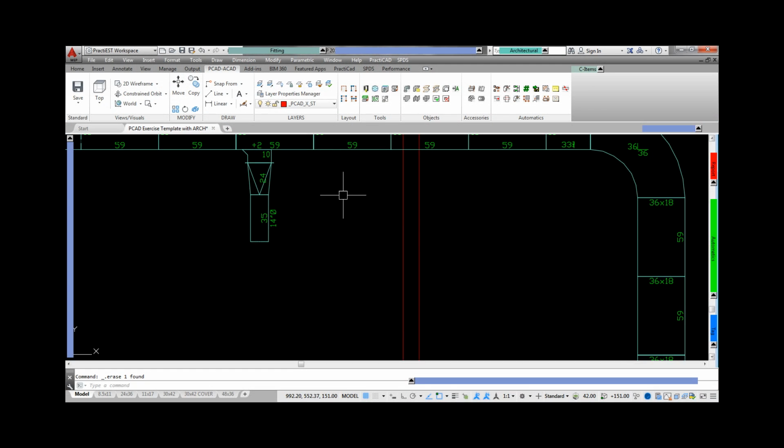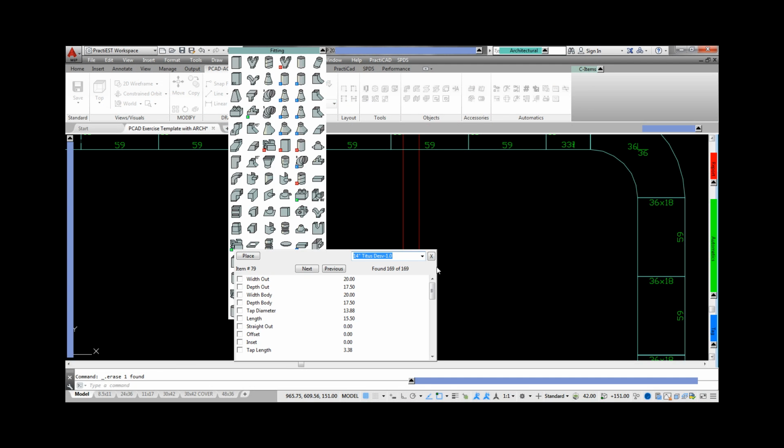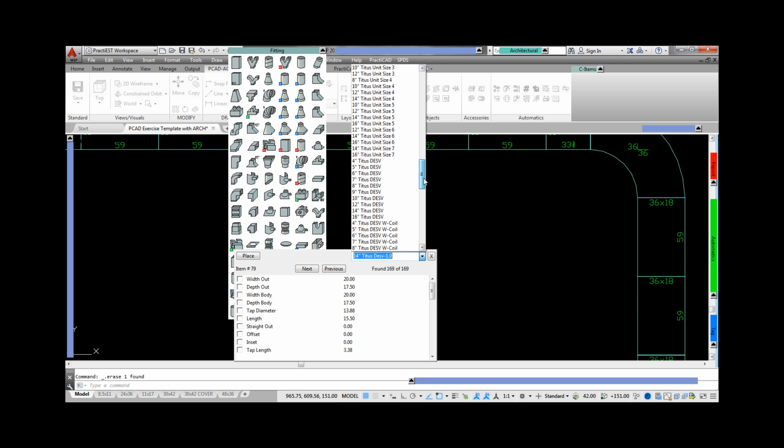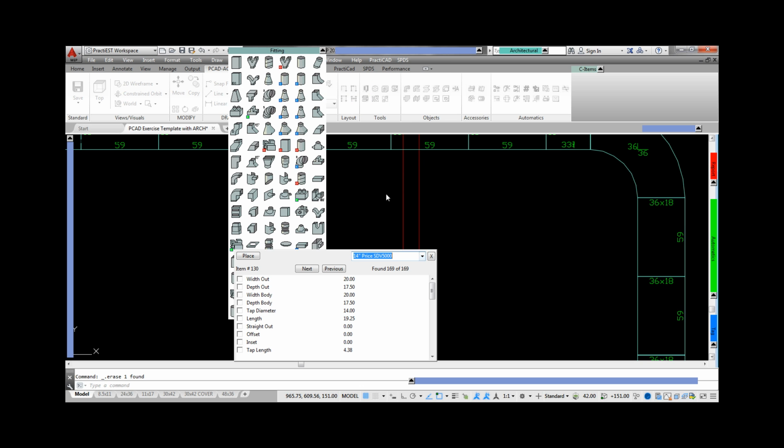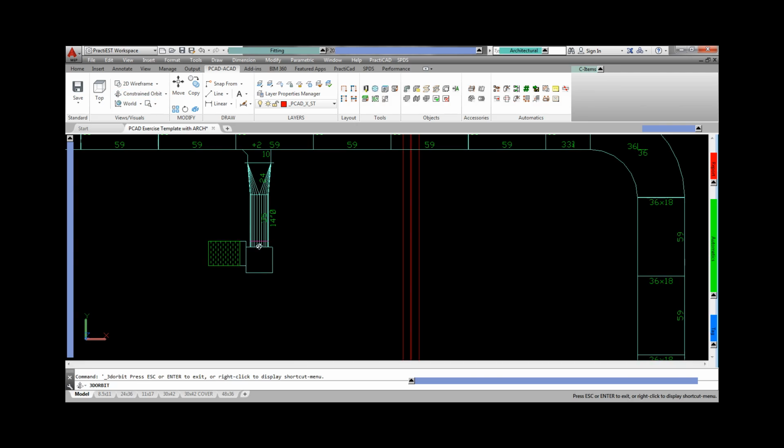Once you have your catalog ready, just grab the icon you assign to it, pick from the drop-down list, and place the entity on the drawing. It's that easy. Here you can see we're placing a VAV box down, and PractiCAD is going to easily snap to the existing duct line. It'll even automatically place the access door for BIM modeling.